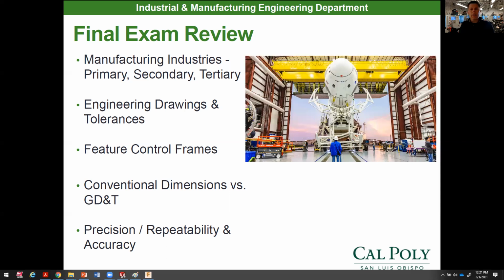So the tolerances on that drawing are definitely going to affect the product's cost, right? Because the tighter the tolerance, the more expensive the part's going to be to manufacture overall. So we have to spend more time in order to get the part to that size or within tolerance, if it's a really tight tolerance. So that definitely covers two other questions right there.